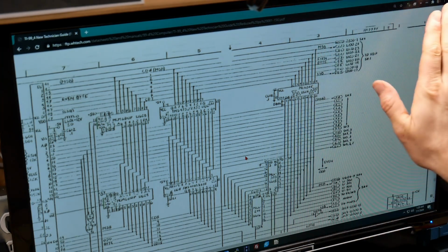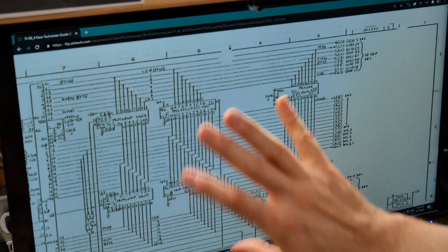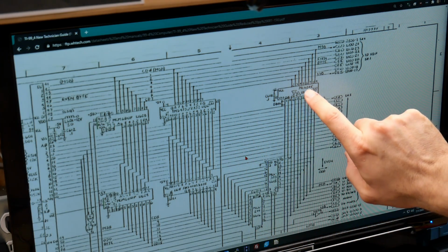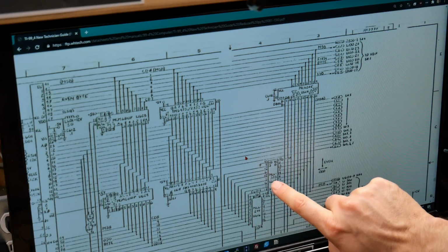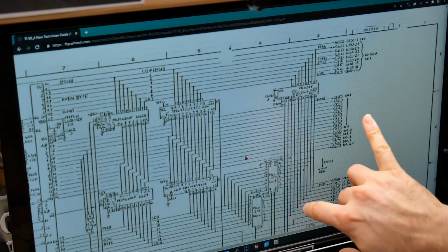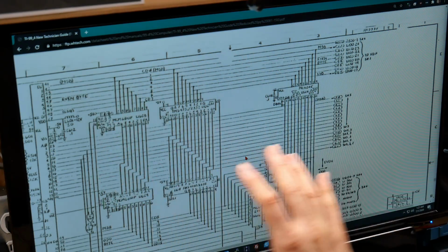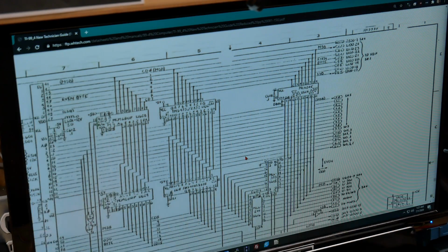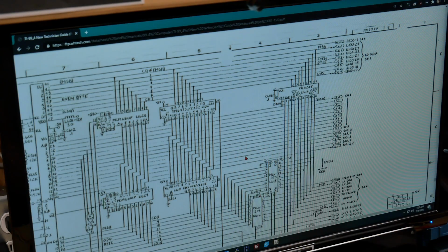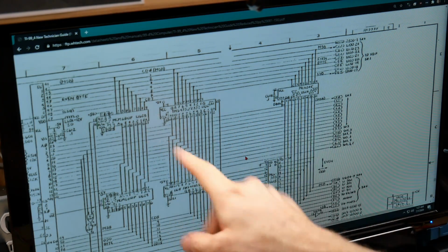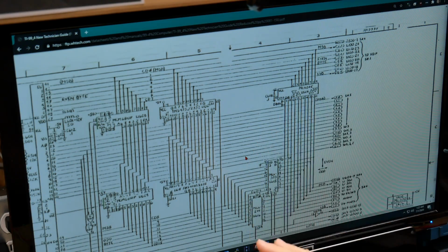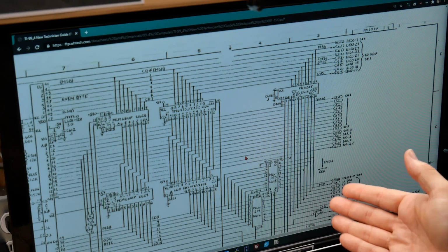I've already ruled out the video display processor because we've switched both of them and it doesn't change the bus problem. I could swap out these 74LS 245s, 244, and 373. Those are standard parts. I have lots of those. So I could switch those out with known good ones. Now, with at least 2 of these chips being problematic, or the CPU being bad, or 2 of these other chips, I have to just start guessing and unfortunately start taking these off the board and seeing if the problem goes away or stays. And that's really, unfortunately, the only way I can do it.